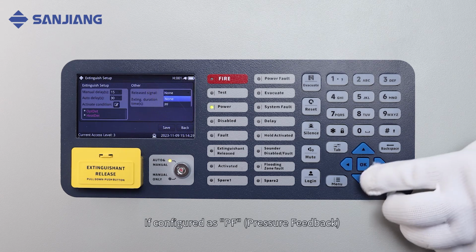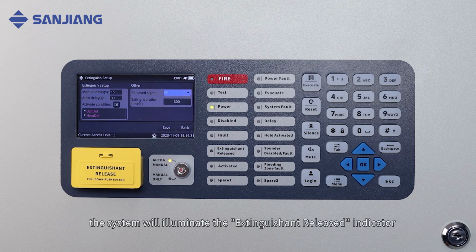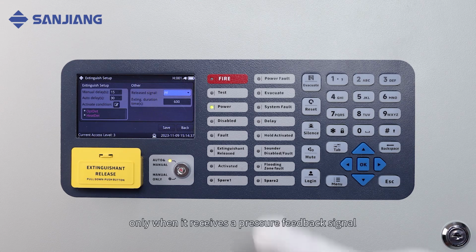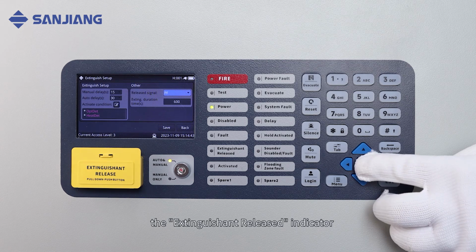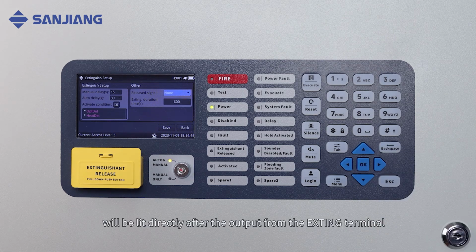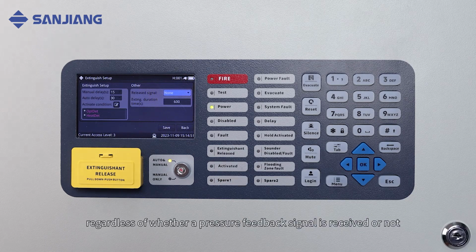Release Confirmation method. This setting determines how the initiation of gas discharge is detected. If configured as PF, the system will illuminate the extinguishment released indicator only when it receives a pressure feedback signal after the output from the existing terminal. If configured as none, the extinguishment released indicator will be lit directly after the output from the existing terminal, regardless of whether a pressure feedback signal is received or not.